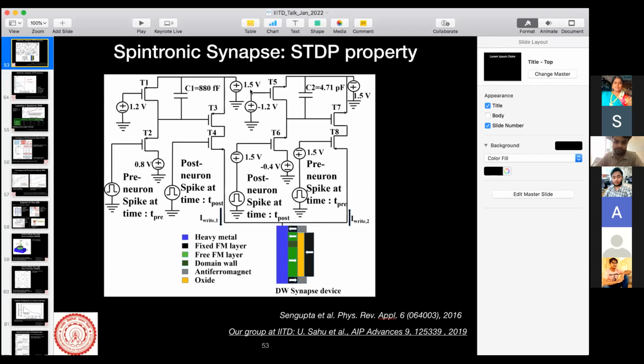Also, sir, how compatible are these devices with each other, say a charge-based MOSFET and a spintronic-based device? At least maybe not in my lab, it is probably not very compatible, but in industry it's fairly compatible, because if you look at STT-MRAM, spin transfer torque magnetic RAM, that's a commercial product. That essentially has the spintronic device, the magnetic tunnel junction, and the transistor built together. It's a complicated process flow, but it works. Okay, sir. But it is not something you can do easily today in the lab, within the academic setting, but in the industry it does work.